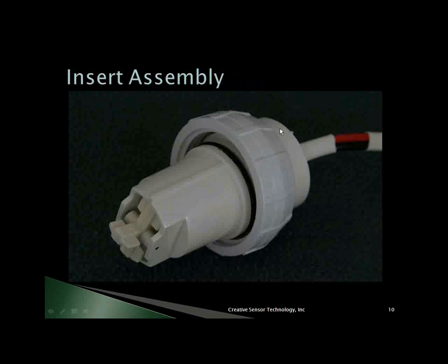The insert assembly, which is common to all sizes, carries the impeller down here. It contains the electronics in a waterproof housing in here. It's sealed into the pipe with an O-ring up here, and it's attached, as I said, with this large screw-on cover that holds it in place and sets it down into the flow at the end of the device.